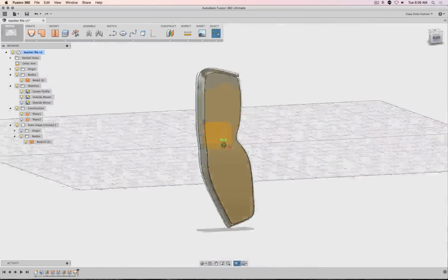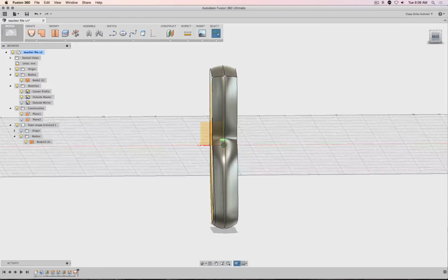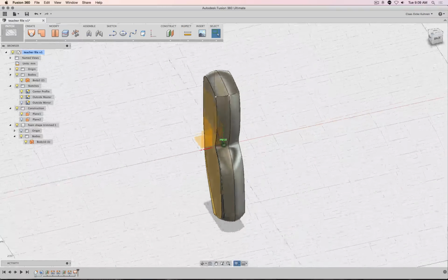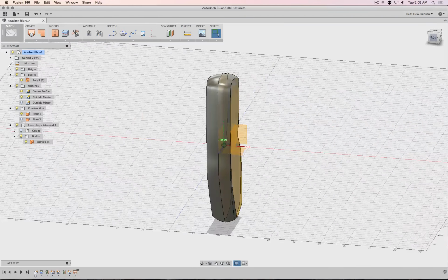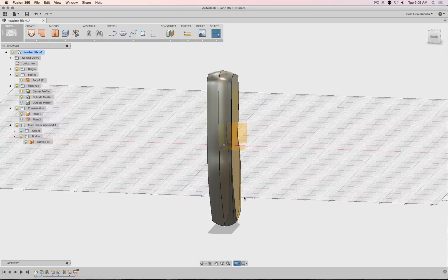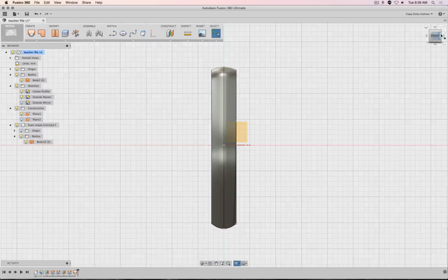And you see actually the way how I rebuilt this in Fusion pretty much is exactly the same way how it was created in Alias. Later the surface was created and trims everything. So that's going to be now my next step. So the way how I can do this, I create a sketch on top and on the bottom, design it accordingly, and then loft it. Maybe I need a sketch in the center as well.